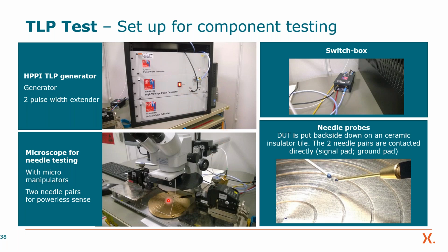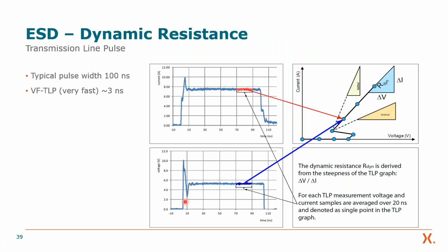Here, this is our setup to actually connect on a wafer to test ESD protection devices for high-speed links, which are basically bare die. But of course, it also works for leaded devices, and we actually very often use it to characterize also internal ESD protections to understand if it works well together with the external one. So this is the result for an example device.